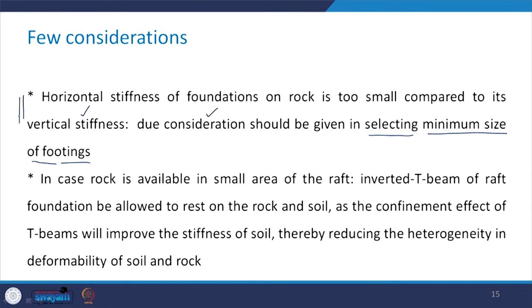Now, in case the rock is available in a small area of the raft, what we do is that the inverted T-beam of the raft foundation should be allowed to rest on the rock and the soil, as the confinement effect of this T-beam will improve the stiffness of the soil and hence reduce the heterogeneity in the deformability of rock and soil. Because let us say that the raft is there and in one portion you have the soil strata and in the other part you have the rock.